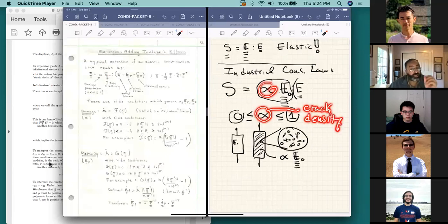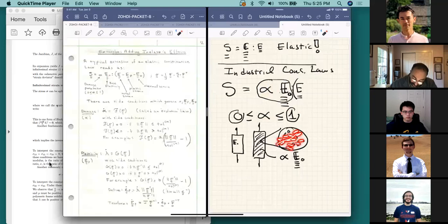So what that means is, as the number of cracks start to increase more and more, as you can see from here, eventually the cracks start to get to such a critical density that they start to connect and the material simply breaks apart. And of course, then the material has 0 stiffness. So the idea is we account for all of that, which is not easy to accommodate in a very, very detailed way.